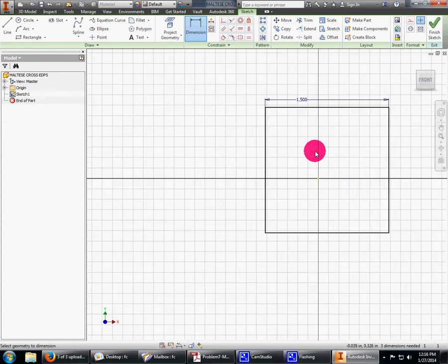And I can look, say, yay, now here's something new also, constraints. Here are your different constraints which you can apply. So you can lock it, make it concentric, you can make it parallel, there's different ones. I want to make it equal. So I want this side and this side to be equal. So no matter what I do,